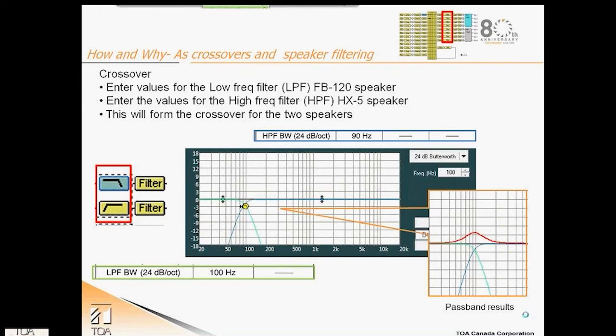This is the possible total frequencies that could be passed by the filter set. Keep in mind that speakers will not be able to pass such a wide range and will have natural attenuation at the low and high frequencies. Addition of speaker filtering will also address the lows and the highs, as we will see in the next step. Any irregularities, such as the bump seen here at the crossover by the red line, can be compensated for later by applying the speaker PEQs.